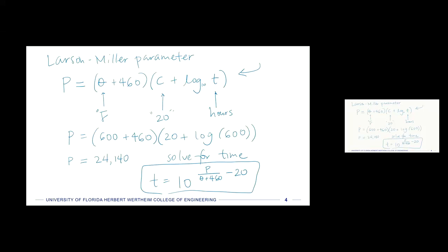Okay, so we'll make a little chart on the next slide that tells us what could be our expected life at those, if it were tested at those temperatures. Right, so we'll have theta, and then we'll have our time in hours. We had 380, 600, and 810. And I solved this, so I got for the 380, I got 5.54 times 10 to the 8th hours, right?